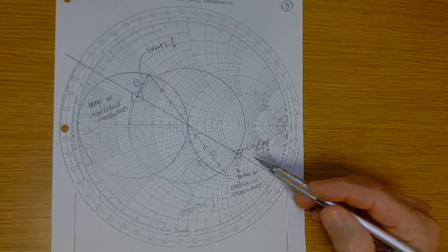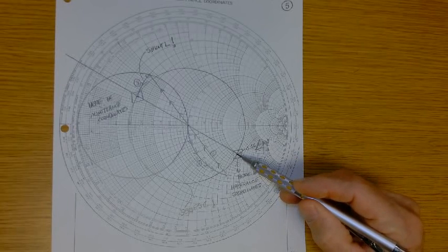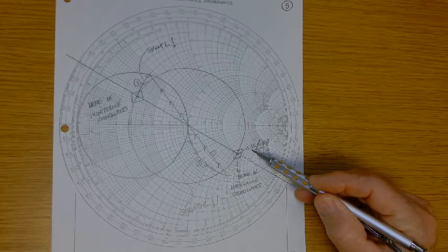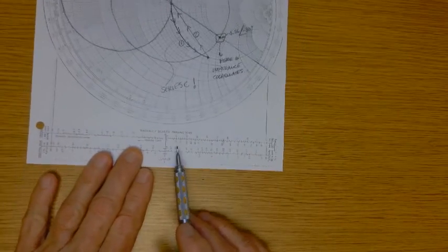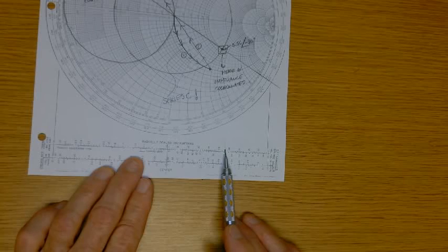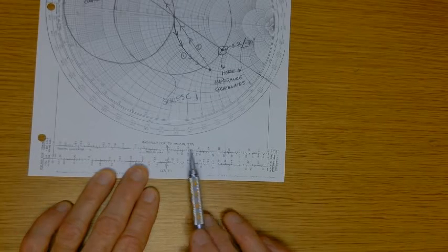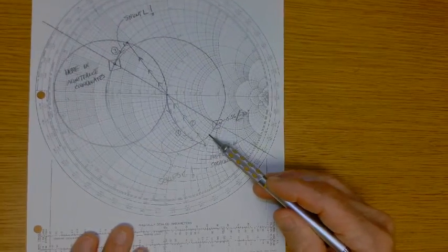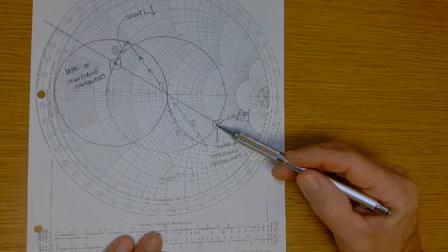Why do I have to get here? Because this is the 0.56 at an angle of minus 30 degrees spot. That's the place where I want to ultimately end up. How do I plot this on the Smith chart? Well, this is a reflection coefficient. So I come down and use this scale and open my compass out till I get to 0.56. So that's my radius. Then I draw my circle, which I've darkened so that you can see it when I scan this. It's already scanned and out on the engineering FTP.